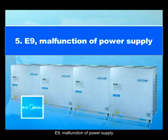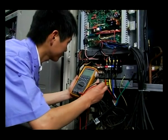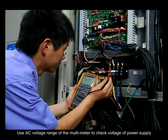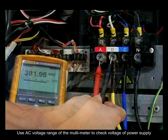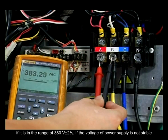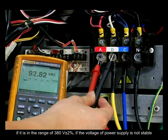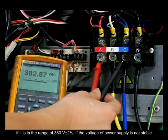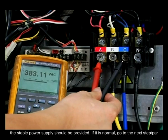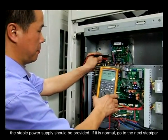E9. Malfunction of power supply. Repair instructions when E9 appears. Step 1. Use the AC voltage range of the multimeter to check if the voltage of the power supply is in the range of 380 volts plus or minus 2%. If the voltage of the power supply is unstable, a stable power supply should be provided. If it is normal, go to the next step.